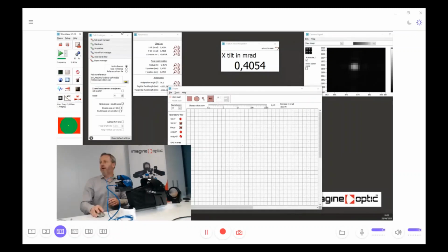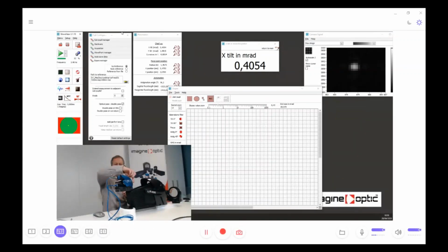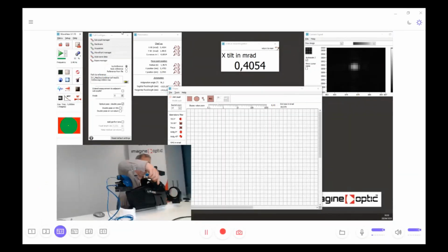Maybe you remember the slide describing this. We have now the R-FLEX, always here a focusing spot, and we have 2 mirrors here. One is here, one is here, and we have a big lens here. So the beam now at the output is collimated with a diameter of more than 100 millimeters, and it is reflected by another flat mirror and set back in the system to be measured by the wavefront sensor, which is here.